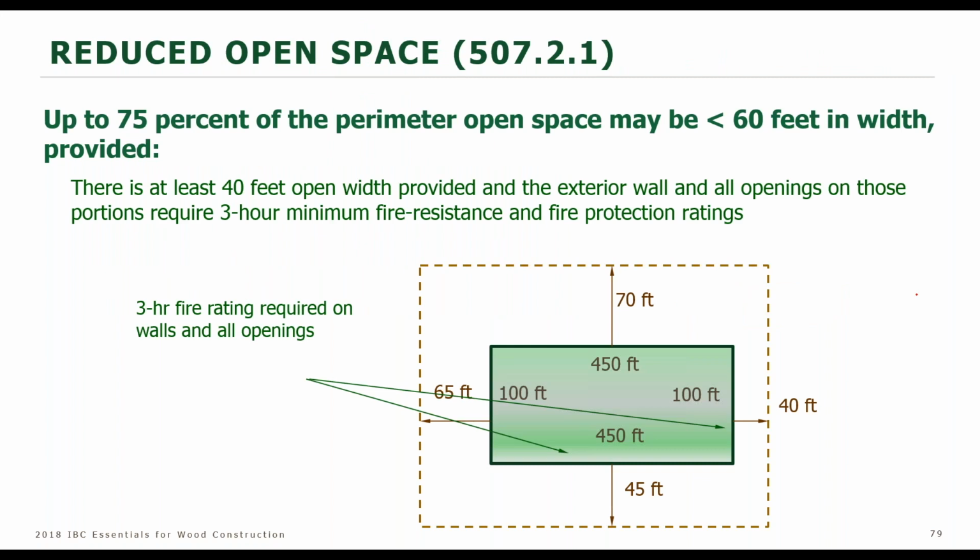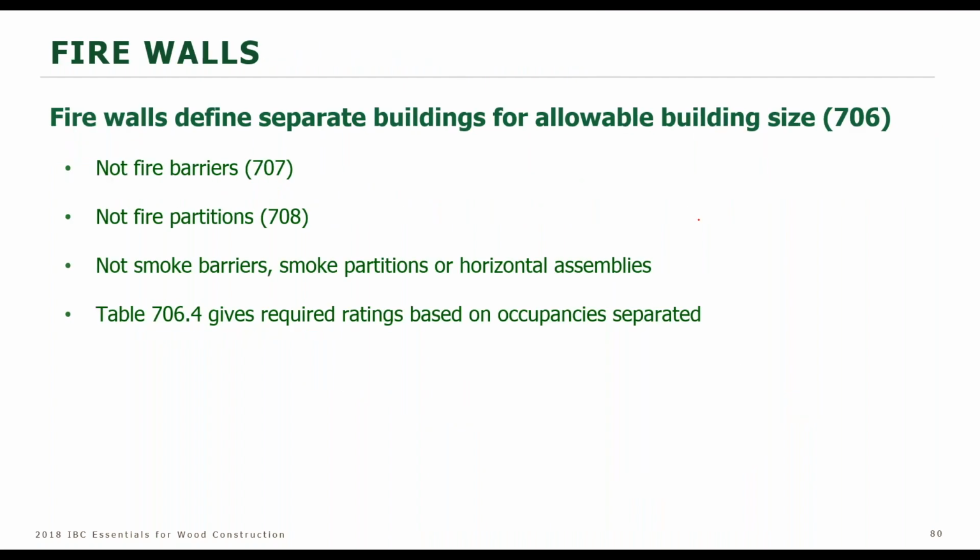If you don't quite have the 60 feet, you'll find a provision in there to rate this wall for 3 hours, and you can reduce it to 40 feet. So there's a little caveat there, 507.2.1, if you need to use it. And you can always, of course, put in a firewall.